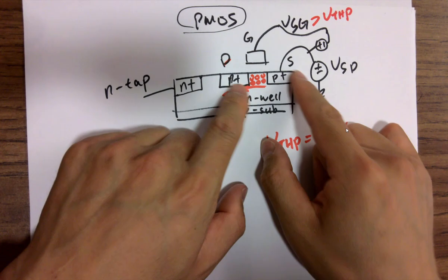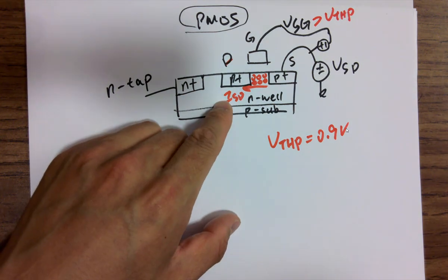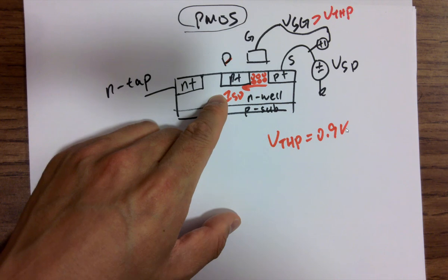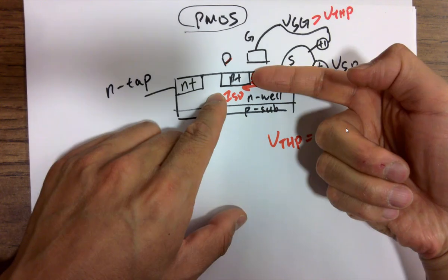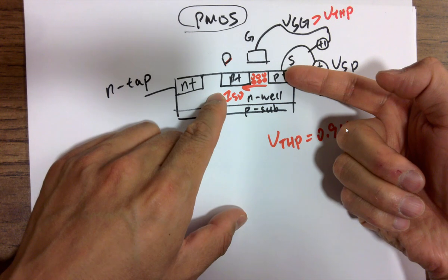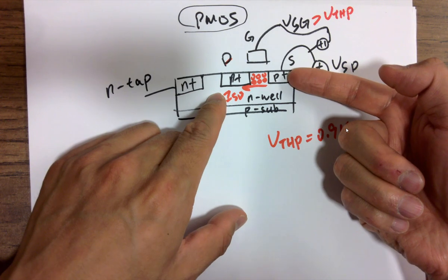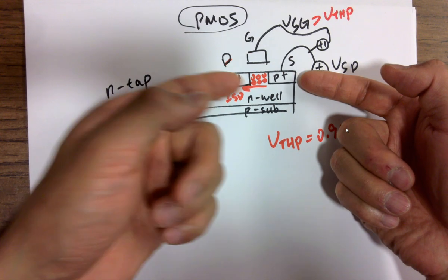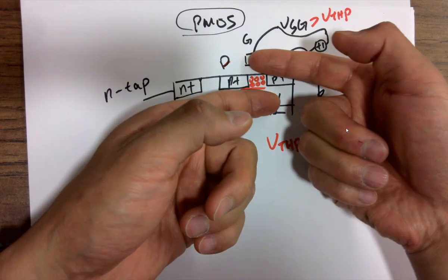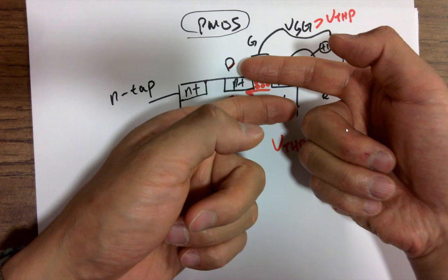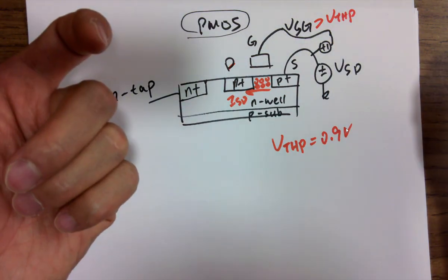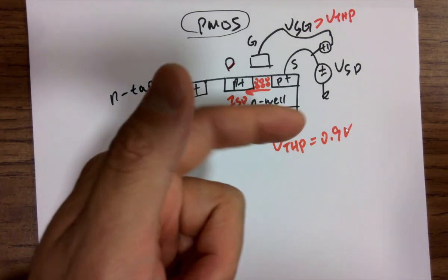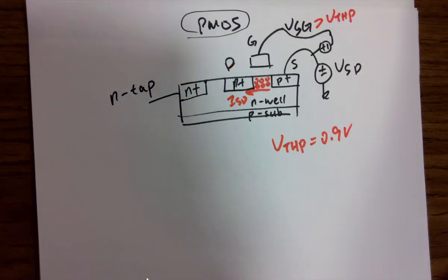like this guy, for example, you get it done, and you right click, add a trace, plotting trace from LTspice, right? If you are adding IS, it's plotting the current flowing into S. No matter which terminal you're plotting, it's plotting the current getting into it. That's how it's being designed. If you're plotting ID, it's actually plotting the current flowing into D. And if you plot ID and IS, you are getting opposite directions of currents, but they are pretty much the same current. You know what I mean? So IS is the current getting into S, and ID is the current getting into D. Just to let you know.